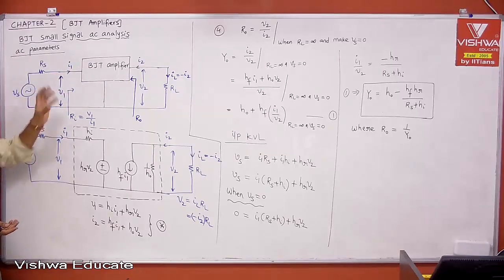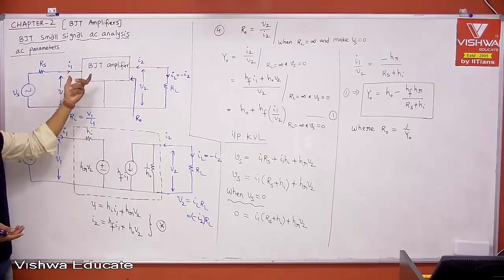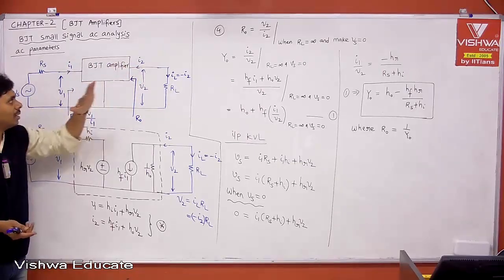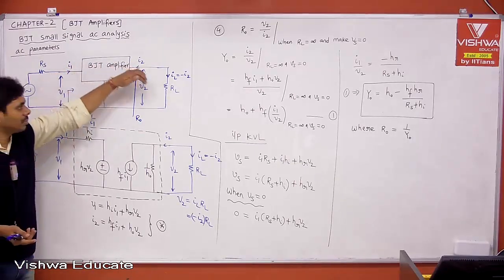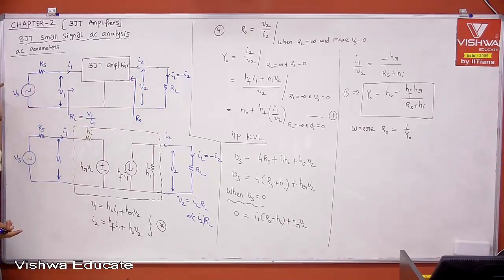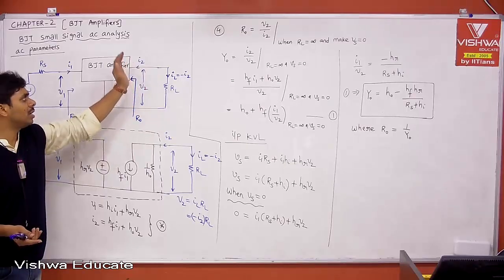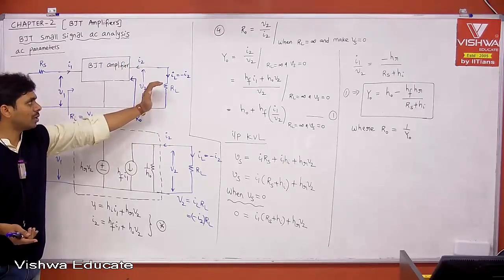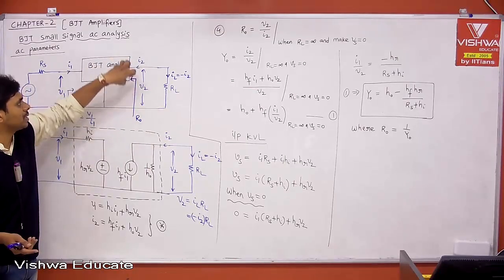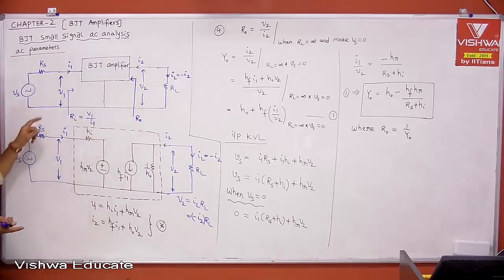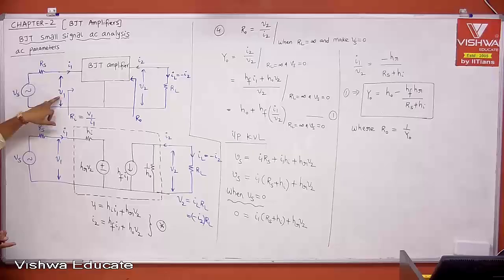Let us calculate, because we already calculated your BJT amplifier core parameters like current entering into the amplifier, current leaving from your amplifier, voltage applied to your amplifier, and voltage coming from your amplifier. But now let's speak with respect to the actual source and actual load. I think the actual load current and actual output voltage match the BJT output voltage and BJT output current, except the direction. That is fine. But coming back to the input, the actual input voltage of the BJT amplifier is not your real voltage source. Because we are exciting with a practical voltage source, therefore V1 has come into the picture.